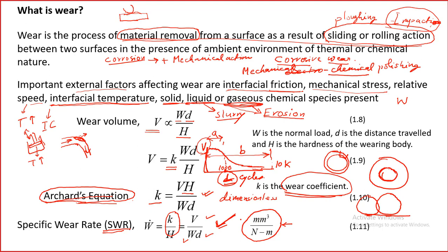So initially wear rate is more, and that comes from this one, because most of the volume loss happened in the beginning, right? And W is constant, so no difference. So we divided V by a smaller number. But if I run the same for 10,000 cycles, the volume initially was large, but after that it didn't change much.